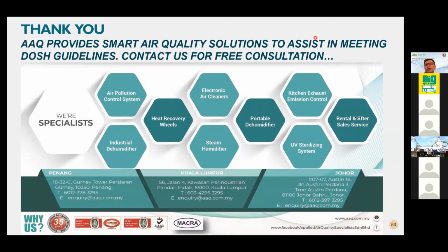For certain areas like an isolation ward, maybe you require 100% fresh air as well, because the risk is very high, with a lot of positive people inside that room. So it depends on which kind of application. It's difficult for me to tell. The OT room is confirmed 100% fresh air. Isolation room, I guess yes, 100% fresh air as well.